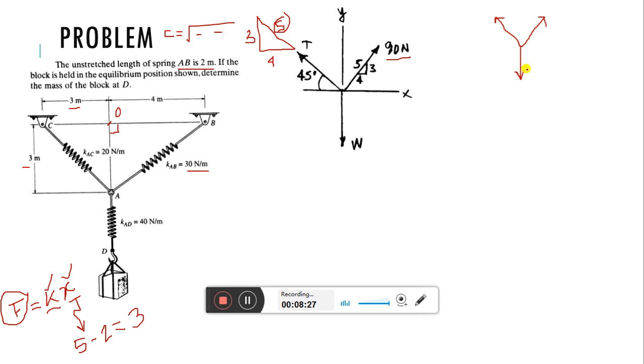So if three forces, suppose this is P, this is Q, and the third one is R. Suppose this angle is alpha, this angle is beta, and suppose this angle is gamma. So for equilibrium, P by sine alpha is equal to Q by sine beta is equal to R by sine gamma. We all know this equation.